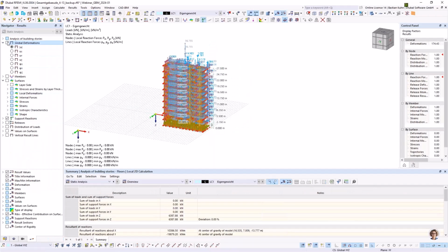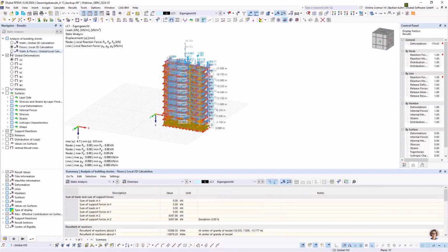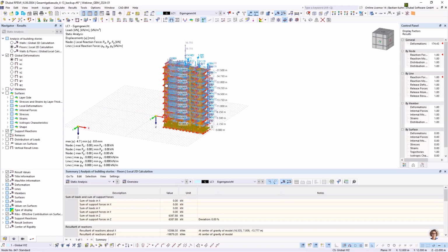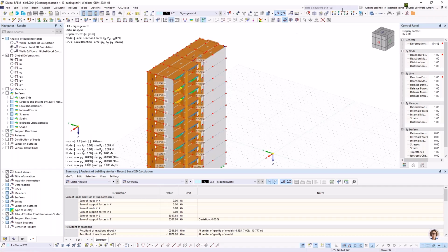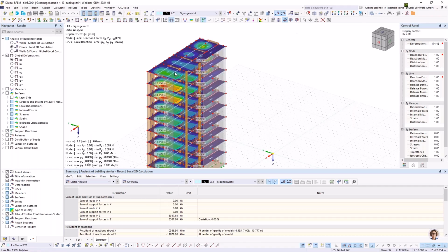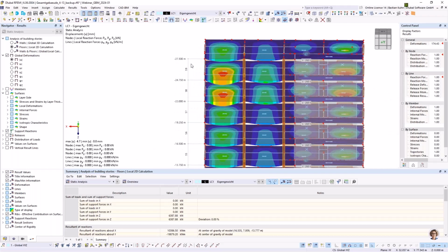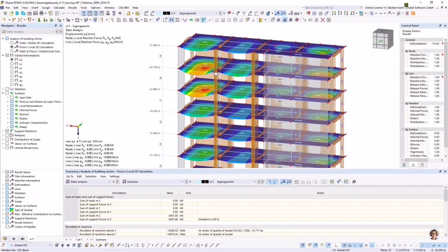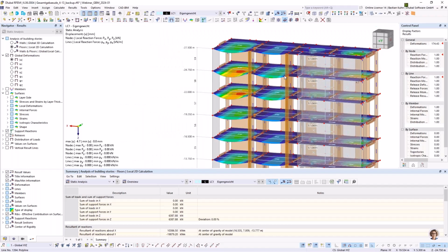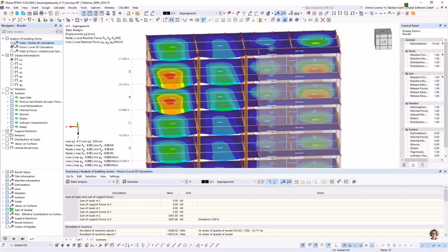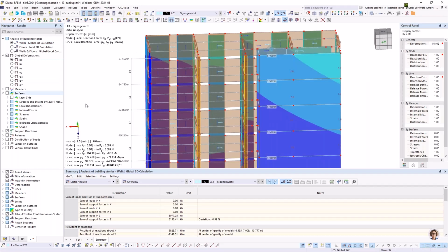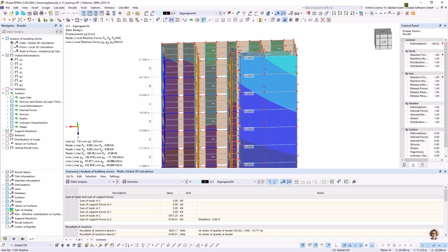All right. So, global deformation analysis. We look for the floors and hope that this is now better in here. Yeah, it looks way better. Yeah, perfect. That's actually what I wanted. So you see now that I'm looking for the floors, you only have here, for the first load case, deformation in the floors and no deformation in the walls. The walls are in this global 3D calculation in here.